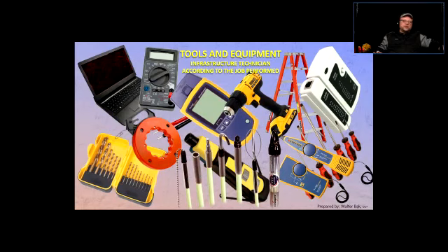Where do you use fish tape? Most of the time, you're going to push that fish tape into a raceway, such as conduit. Okay? And then you're going to push that enough. This one is a metallic one, but there are also fiberglass ones. So that thing is rolled into that roll, and you just pull it out, and when you're done, you just roll it back into it, and you can store it away.